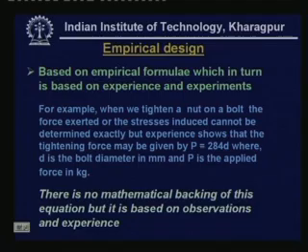When we tighten a nut on a bolt, the force exerted or the stresses induced are very difficult to find out exactly, but experience shows that the tightening force may be given by P equals 248 D, where D is the bolt diameter in millimeters and P is the applied force in kg. Surprisingly, there is no mathematical backing of this equation, but it is based on observations and experience.